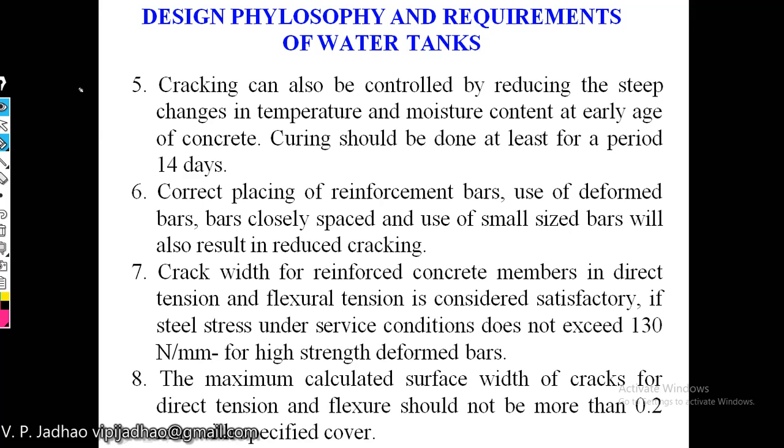Along with all these requirements, if we provide correct placing of reinforcement bars, use deformed bars, closely spaced bars, and small sized bars, it will also result in reduction in the cracking. Now the crack width for the reinforced concrete member in direct tension and flexure is considered satisfactory if steel stress under service condition does not exceed 130 Newton per mm square for HYSD deformed bars.